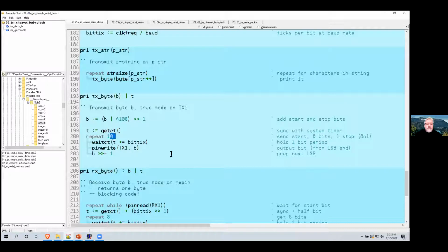And to be honest with you, I often do this just in case I do something silly. So here, pop quiz. If I change this to 11, am I going to have a problem? I need the Jeopardy quiz theme to be playing now. That leaves a 0 at the very end? Yes, it will. I'll send 11 bits, but the last one will be 0, which will look like a start bit to the receiver and will create a problem.